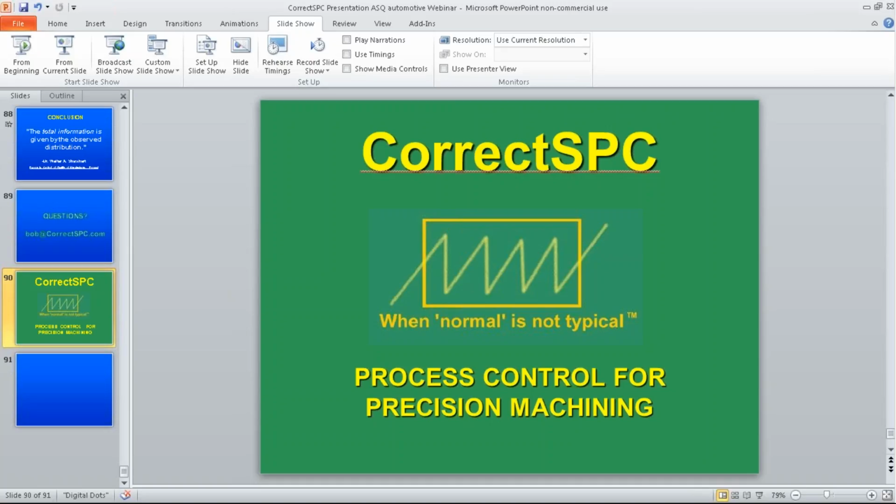Absolutely. For capability calculations, do you use all data points? Any data points you don't use for it? Any tips or suggestions and rationale you recommend? Well, the beauty of this distribution is the points that you use are your control limits. And the other beauty of that is you don't have to recalculate, because it doesn't change. So you have, for example, a 1.33 is using 75% of your tolerance as your control limits.